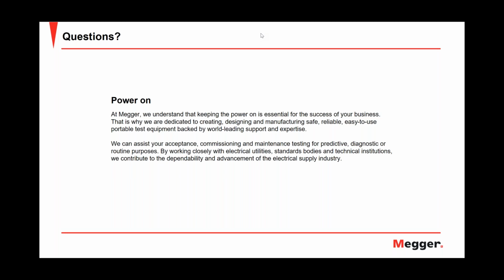And how high do you actually adjust the voltage? Well, first of all, you have your cable rating. You saw Javier's numbers. Let's say we take a 25 kV class cable that typically has an operating voltage of 14.4, but that is RMS, so it's the AC rating. Now that is associated with roughly 19 kV peak, right? So the cable sees at 60 hertz 120 times every second 19 kV.